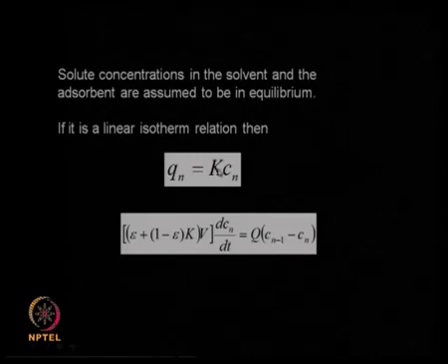So, by putting in the value for Qn like this, we can rearrange the equation to get a differential equation like this. Q into Cn minus 1 is the amount of solute entering stage n, Q into Cn is the amount of solute leaving stage n. This is equal to a big number here, dCn by dt. Now, this is called a differential difference equation, because I can have many equations like this for each stage: stage 1, stage 2, stage 3, stage 4.